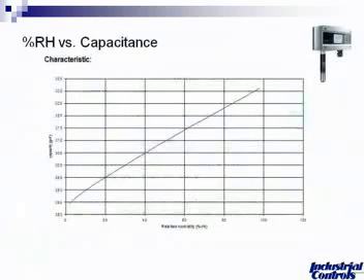In this example, you can see that this particular capacitive sensor is very, very linear. You can see down from about 285 all the way up to 340 picofarads. It's very linear, and then today's digital electronics allow you to enhance that linearity or even better to give you better accuracy.